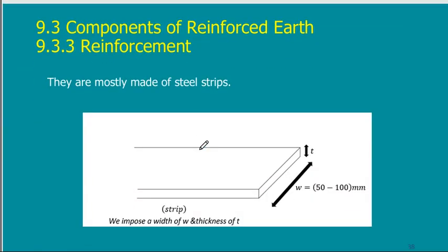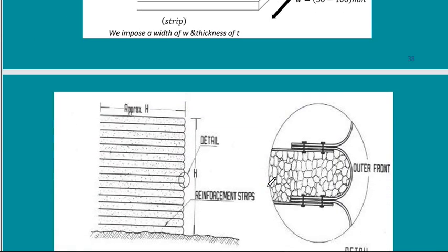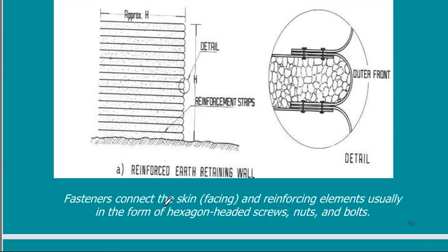The other thing that we design is the reinforcement. Is it a strip or is it a grid or is it a geotextile layer? Anything I design. This is just a shape to show you how we wrap the soil inside. If I use reinforcement that is not strips, I use geotextile. The geotextile helps me in wrapping these systems.